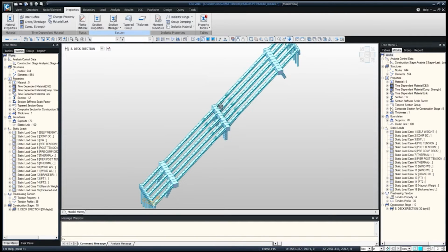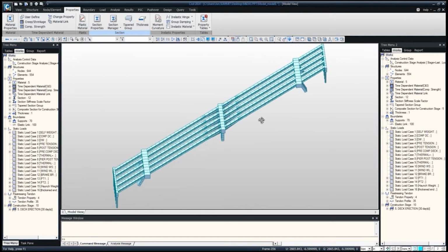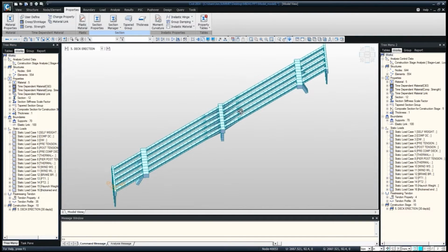Now, because this is a straight girder, what we can allow that to do is simply rotate, and that's what that reduction takes into place. We reduce rather than reinforcing for the entire element in its full stiffness, we assume that it will develop some minor cracks while still allowing the structure to remain in static equilibrium. Allow the pier cap to rotate and still stay stable.